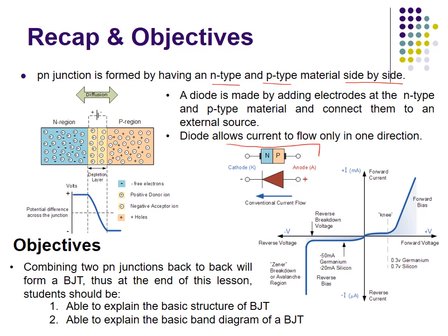This figure shows the current voltage characteristics of a diode. We can see that the current increases only when the diode is biased with forward bias. However, we can also observe negative current being produced under strong reverse bias, which means at this state the breakdown happens. We have also discussed the band diagrams of the PN junction and the representation of carrier flows and their currents that can explain the IV characteristics.